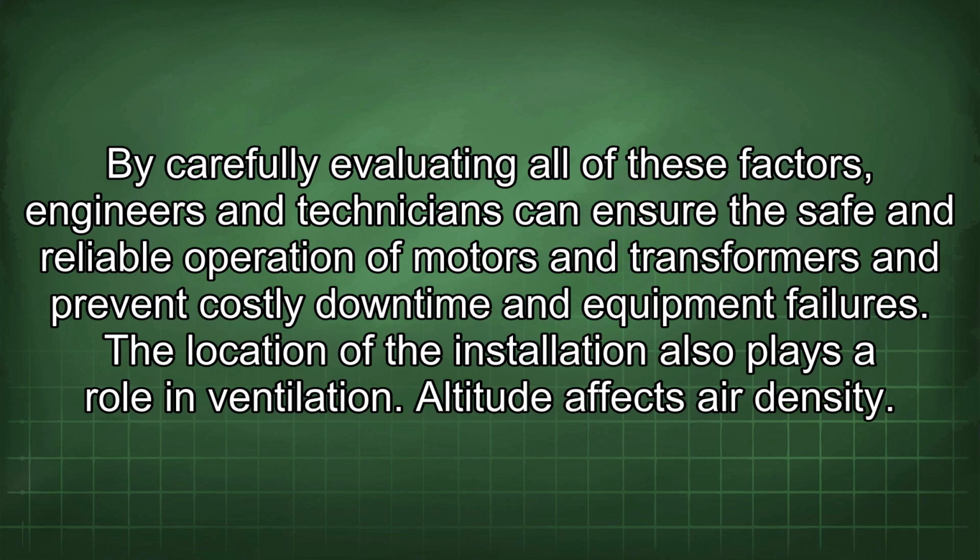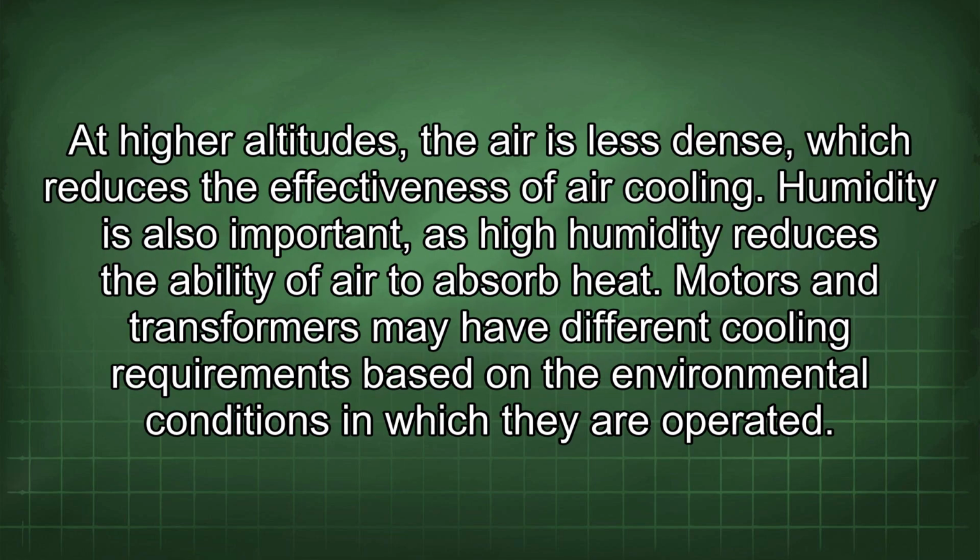The location of the installation also plays a role in ventilation. Altitude affects air density. At higher altitudes, the air is less dense, which reduces the effectiveness of air cooling. Humidity is also important, as high humidity reduces the ability of air to absorb heat. Motors and transformers may have different cooling requirements based on the environmental conditions in which they are operated.